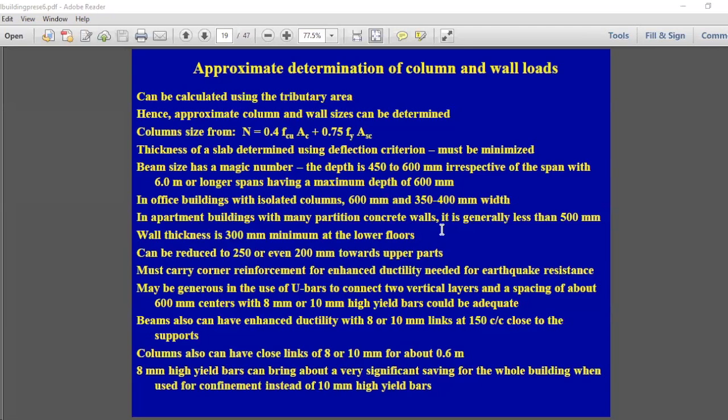Because when you consider the floor-to-floor height, the floor-to-floor height depends on the clear height that we generally like to be about 2.7 meters, then about 300 millimeters for the AC duct, and then the beam depth. So if you are going to have 0.6 meters, this will give 3.6 meters. If you are going to have 0.8 meters, you will end up with 3.8 meters.